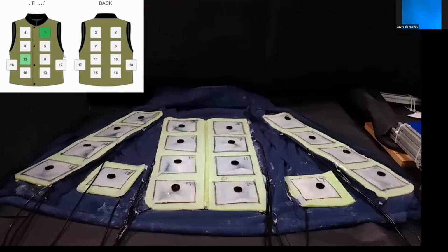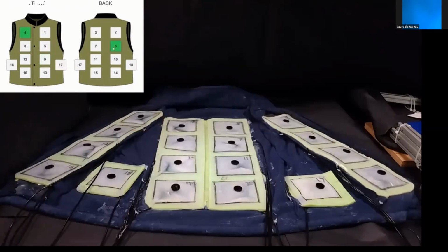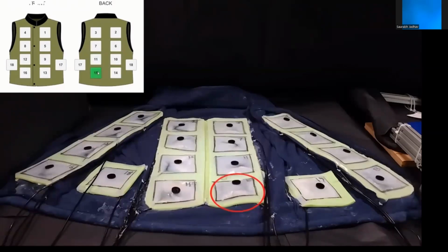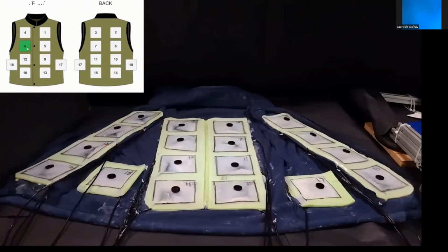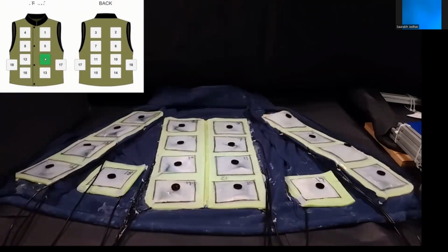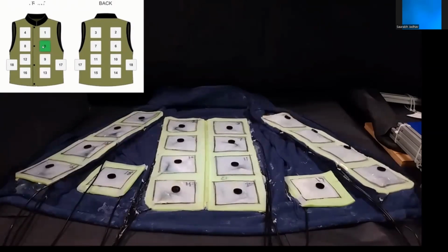We also demonstrate the implementation of the fluidic matrix circuit for controlling a haptic vest consisting of inflatable airbags. These airbags provide force feedback to the user when the bag is inflated. The fluidic logic module generates a pressure signal by addressing the corresponding row and column in the fluidic matrix circuit. This pressure signal is used to inflate the pouch. Then by addressing the same row and column connected to the pouch along the fluidic matrix circuit, the pouch is rapidly deflated to give a sensation of being hit by a soft object.